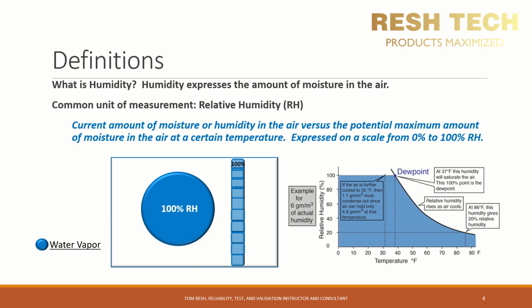This is a good thing from a comfort standpoint. In this example, a dew point lower than the ambient air temperature will leave you feeling more comfortable and less sticky. This is not always the case in the real world, however. As with places like Florida, there is a lot of liquid water sitting around, just waiting to get evaporated. And as air temperature increases, its ability to hold moisture increases as well, which makes you feel all wet and sticky. Likewise, notice that the dew point in this example increases as the temperature decreases.